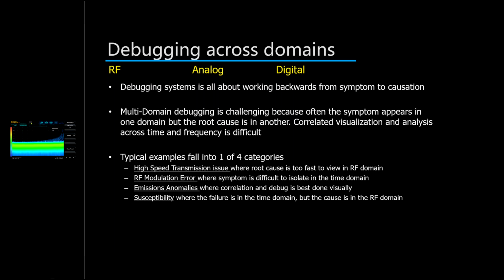And we'll see what I would call modulation errors, or issues where the symptom is a subtle modulation offset in frequency or amplitude or phase. It's really just too difficult to look at in the time domain and really visualize just with a scope.